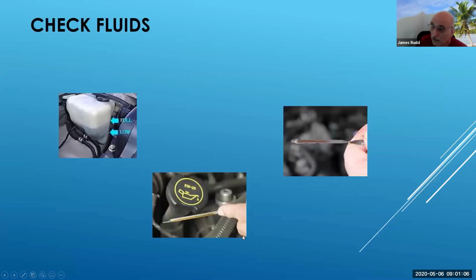And then it's just this really quick check of your coolant levels. I pop off the cap. I'm not talking about the pressure cap on the radiator right away. If it's hot, I'm not even thinking about opening that up. I don't want to get burnt, and I don't want anybody else to get burnt. But if you look at the reservoir, the little surge tank, and look inside, if it's been driven to your shop, it should be up to the full level. If it's not, it's low. Then we can have a potential problem.